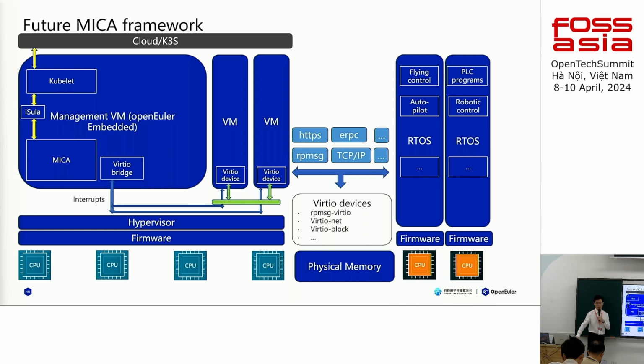Okay, so I would like to show our envision of the future framework. So firstly, we will deploy many OS based on the homogeneous core cluster with a type 1 hypervisor. Because it's a type 1 hypervisor, even though different virtual machines are isolated, they actually have a management VM for managing the whole virtualization system.